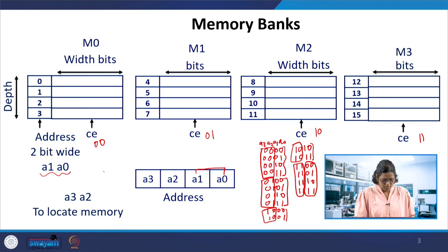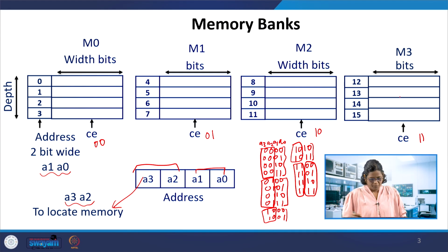So these last 2 bits are used to locate the memory, meaning which one out of 4, and A0 = 0 and A0 = 1 decide which location in one memory, and which location in another memory, and so on. Now we will see these 4 memories, how we code them in Verilog, how we store the data, and then how we are going to retrieve the data.